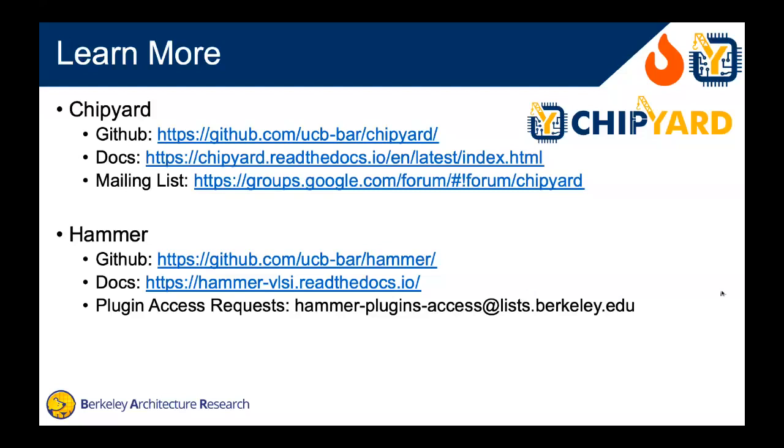Is it applicable to a plain Verilog flow? So you can use plain Verilog going into Hammer. You won't get some of the benefits of these higher level APIs that are based on Chisel annotations and FIRRTL. But originally Hammer was separate, and so it still maintains those capabilities of just running on Verilog.